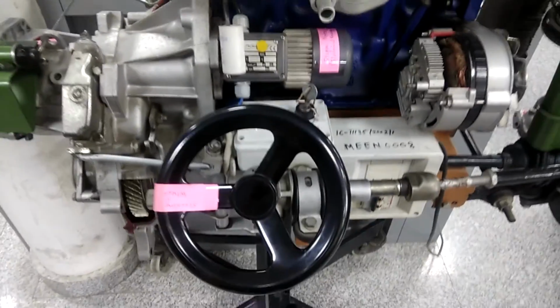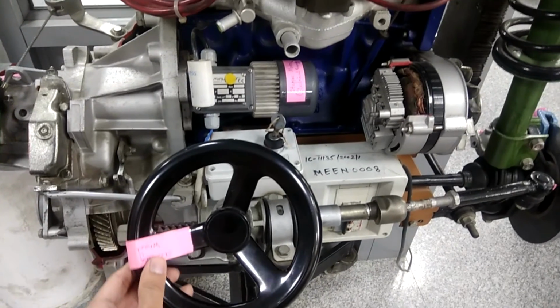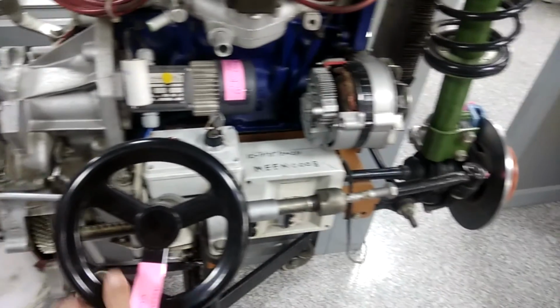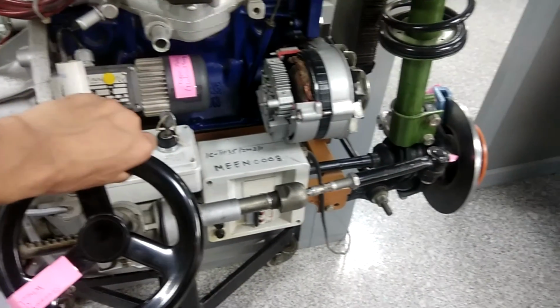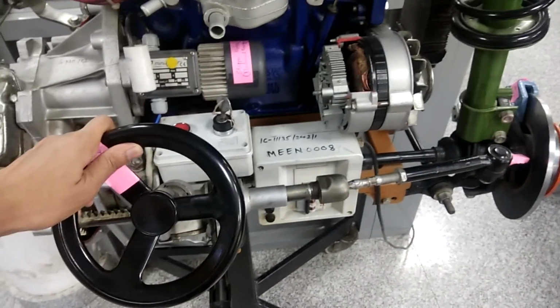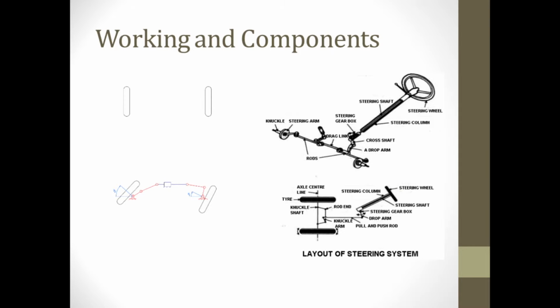When the steering wheel operates, the knuckle moves to and fro. The end of the tie rod and knuckle are connected to each other. Both the ends of drag links are connected to tie rods. A ball and socket joint gives the required movement to the joints between the rods, the drag links and the drop arms. When the vehicle moves, the drop arm develops vibration. Shock springs are used in ball and socket system to absorb these vibrations.